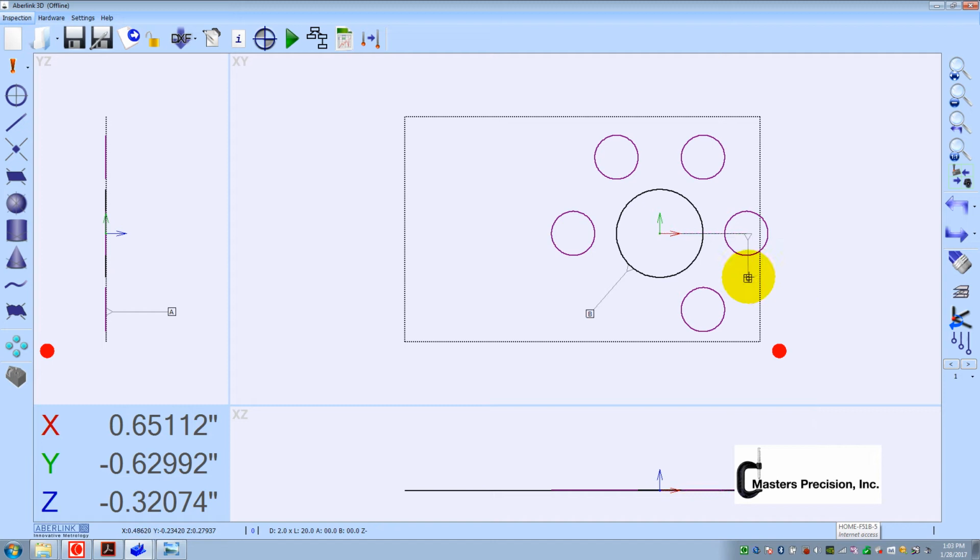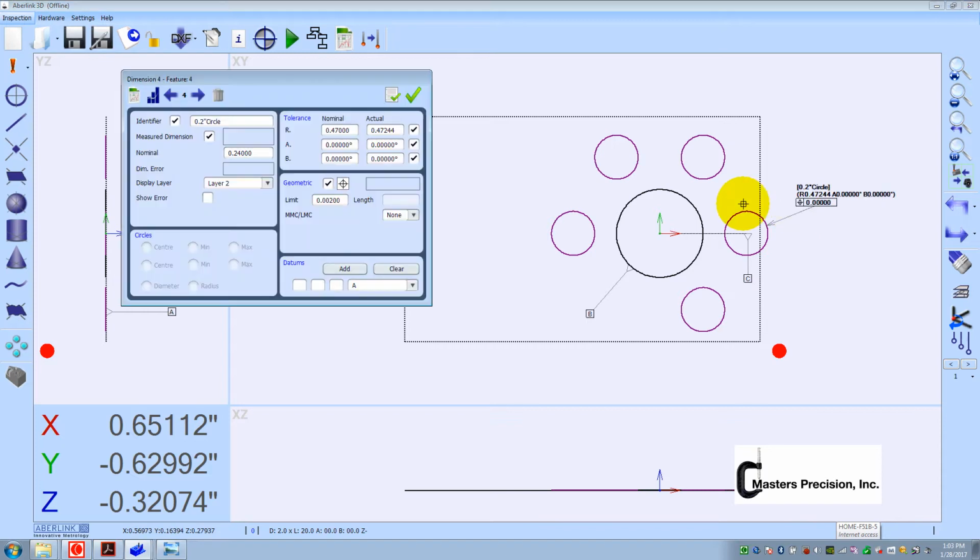So now you can see where datum C is the line. So I'm going to double click on the edge of this, right click, position, polar. We'll bring it over here. Now I right click on the leader line. You want to do your geometric work first, otherwise it unchecks boxes on you. So we'll go MMC.